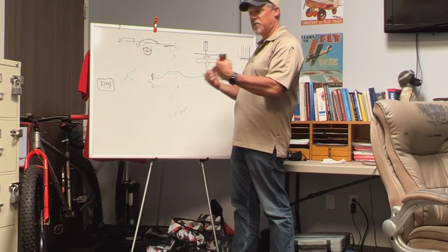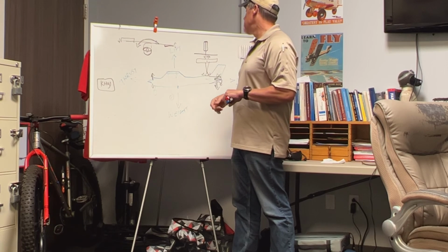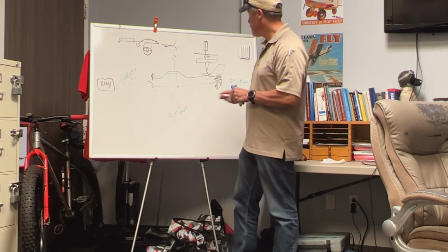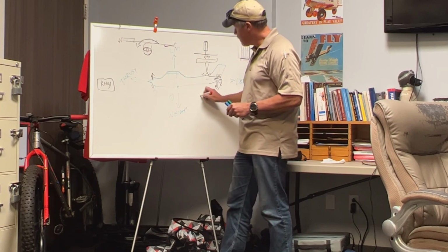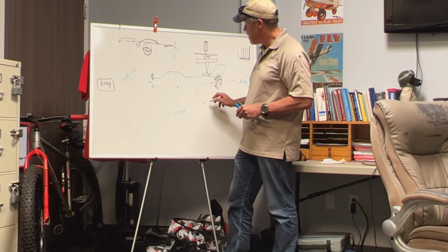So when we go up and fly, we're going to do some demonstration on the controls, really learn what they do, how they work in conjunction with each other. Probably do a dynamic stability demonstration where I'll show you the stability of the airplane. So we're going to go up, we're going to pitch the airplane up, nose up about 15 degrees, and all we're going to do is just let it go.